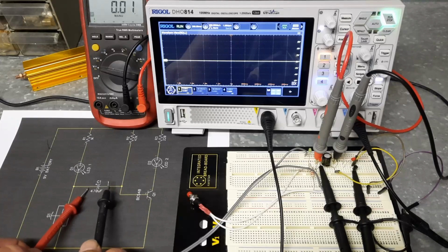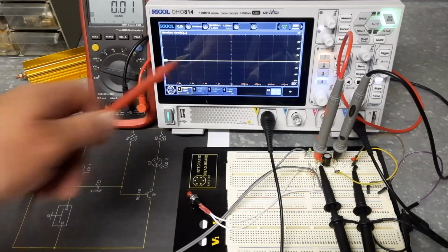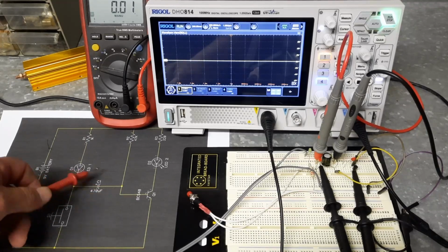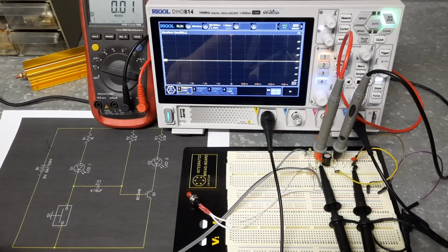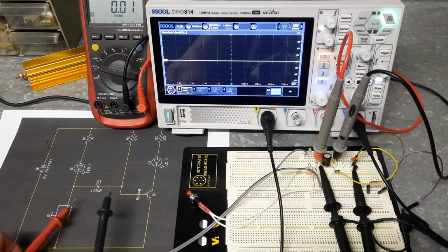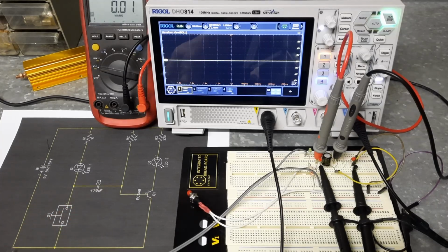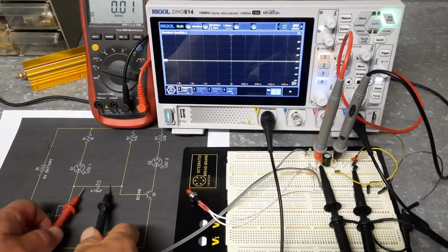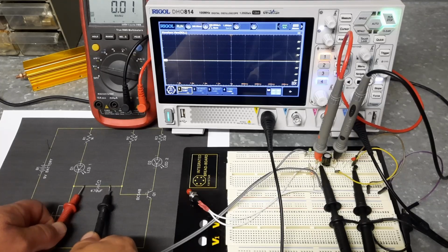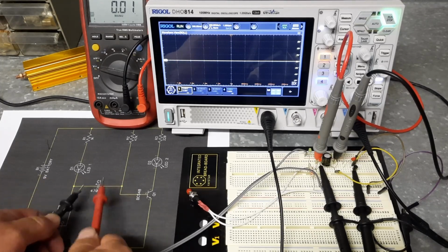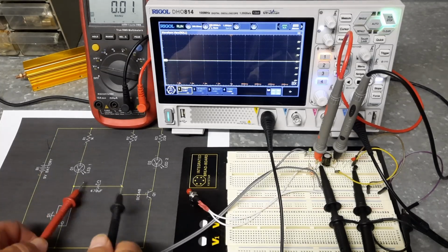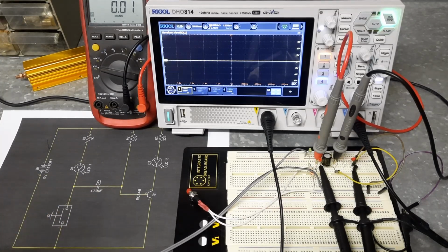So what you'll see is obviously the yellow trace will rise, and that's the scope connected from here to here. So you're going to see the cap charge. You'll see it go up on here, and then when we push the button and hold it, you're going to see this thing fall through 0, and then take on a negative charge, which means if we reverse the two leads, there'd be a positive charge across this. So this thing is going to have a bit of a negative charge in it.